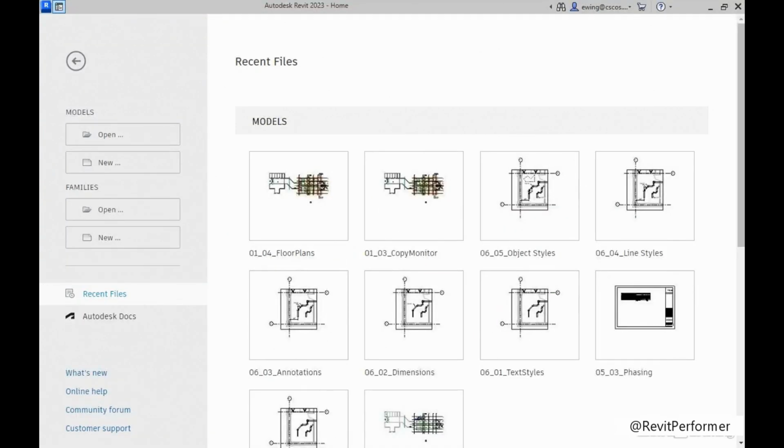There may be a time where you can't find a plan view in the project browser, but know there's a corresponding level. Also, if the level's been copied using the Copy Monitor function, Revit does not automatically add it to the project browser. You gotta do that manually. You'll also need to allocate the discipline as well as the subdiscipline.